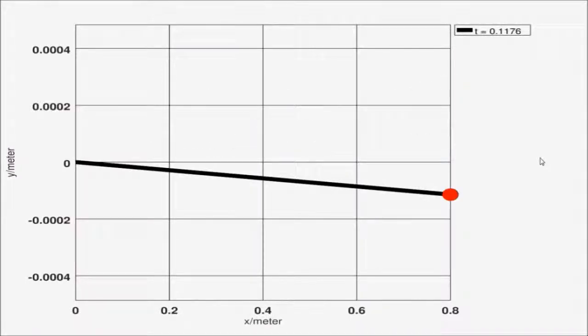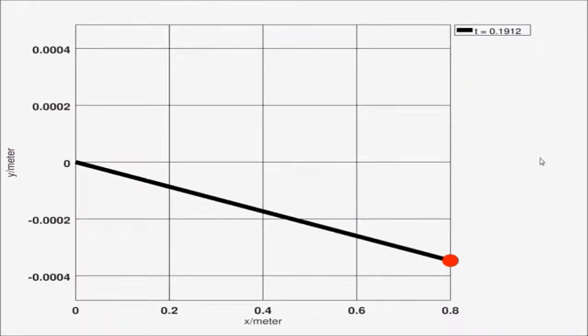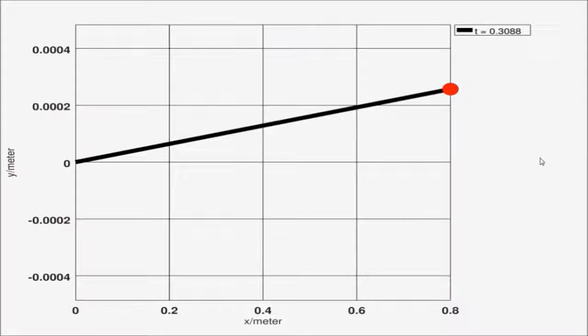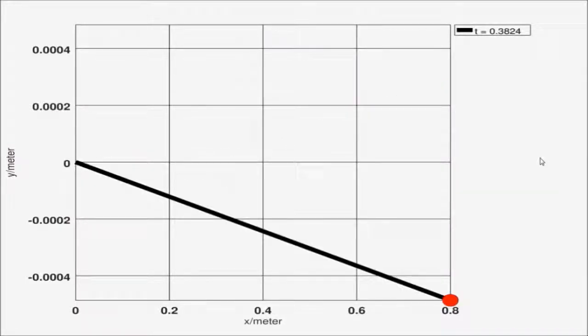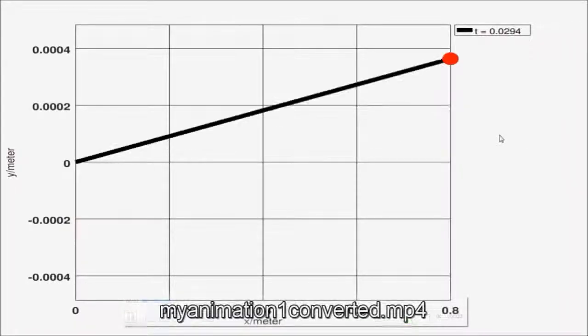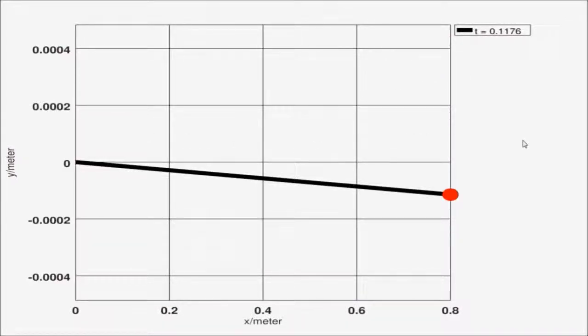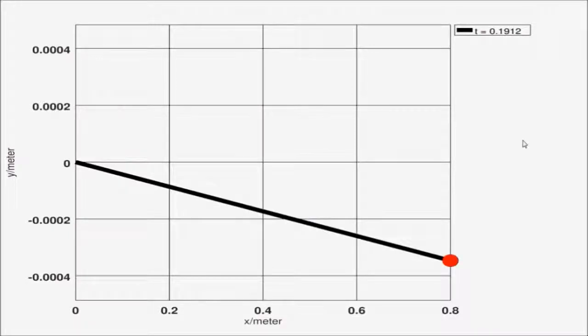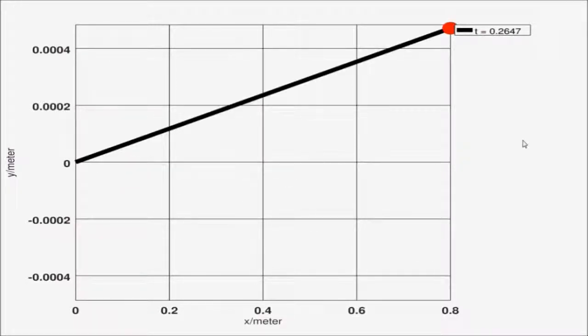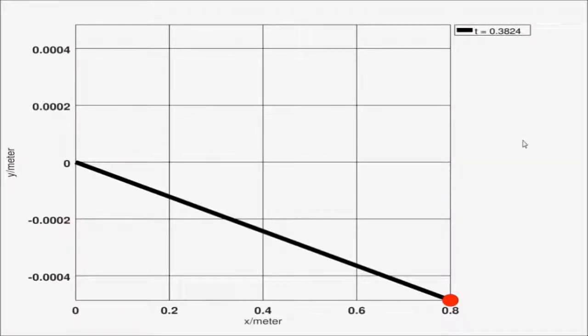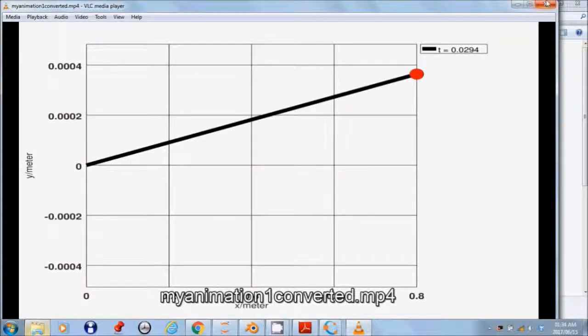So in the course, I demonstrate how to analyze equations using Newton's equations of motion. You derive some equations. You can work out the natural angular frequency, the damping factor, and so on and so forth. So there's a system of differential equations. You would physically solve it on a computer numerically, and this would result in a physical motion at the end of the day. In this case, I simulated it for about half a second using the data. So that is how you would do an actual simulation.